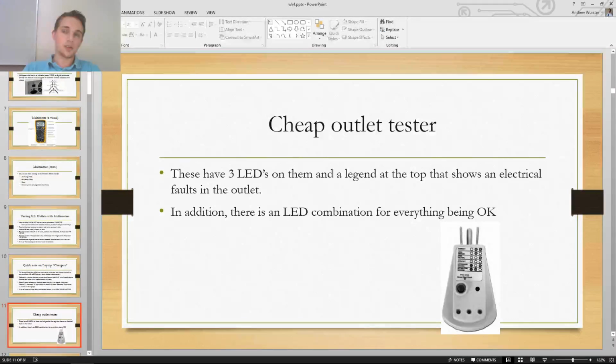and that'll tell you if it's capable of doing that. The amount that surge suppressors can handle is measured in joules, which is a measurement of electrical energy. I don't know the formula off the top of my head, but that's how they measure that. So the more the better in this case. They said look for a minimum of 800, but the guy who actually wrote the book, Mike, says he uses about a 1400 joule surge suppressor just to play it safe.